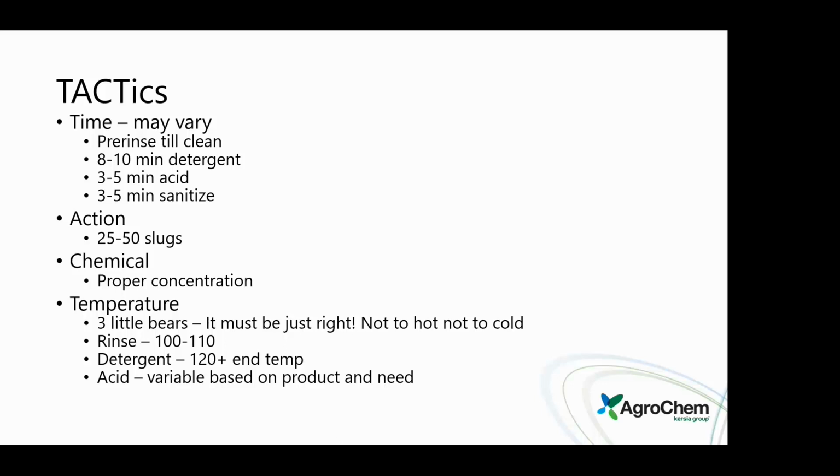And the acid, that can be based on what acid you're using. We definitely hear of hot acid washes and such. The hot in hot acid wash stands for a couple of things. It's not only the hot temperature, but it's a hot amount of product, putting an additional amount of product in and doing a good strong wash at that point. So depending on the types of acid you're using, that temperature can vary.